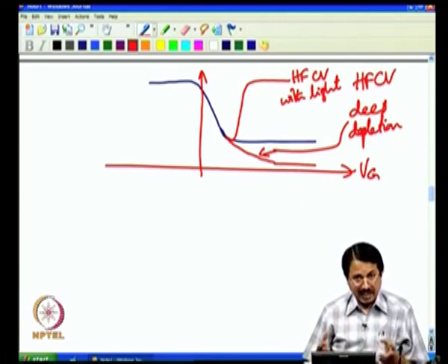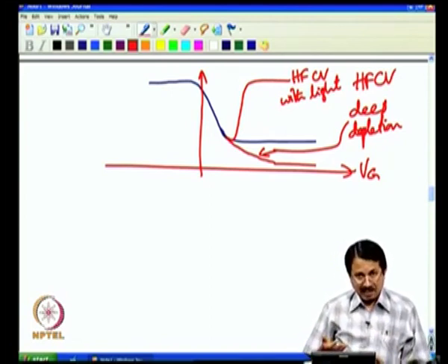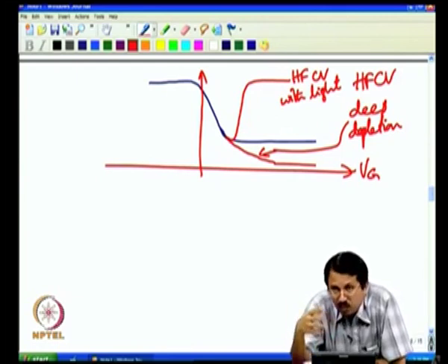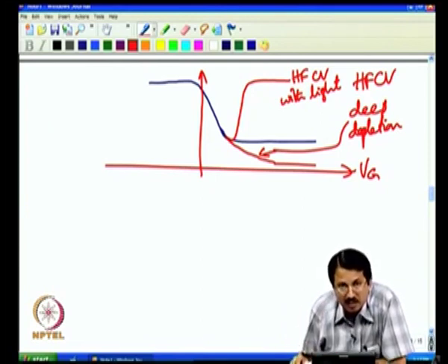It is like photovoltaics, right? I mean, you have a light, you generate electron hole pairs. When you did not have any light, that is the thermal equilibrium, given the room whatever ambient temperature of the measurement, that temperature has thermal generation. The generation is only due to the ambient temperature, but if you have light, you will again get erroneous capacitance.